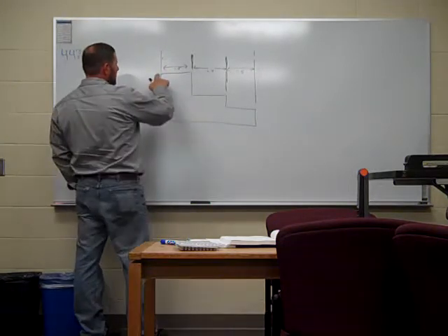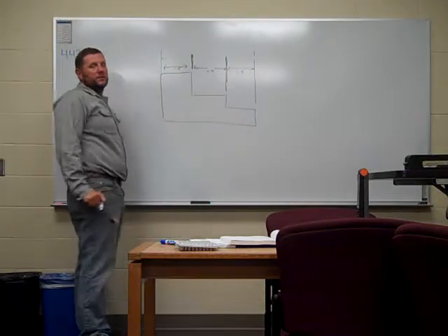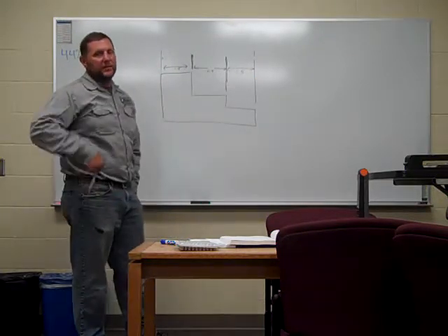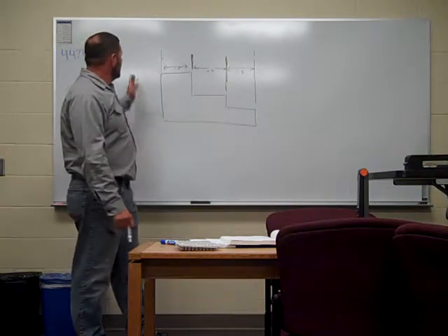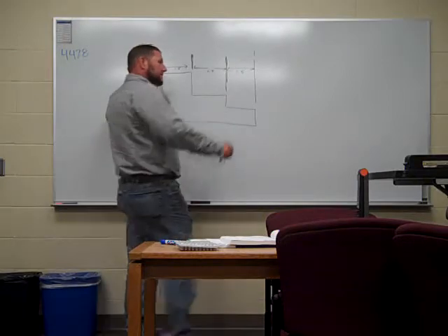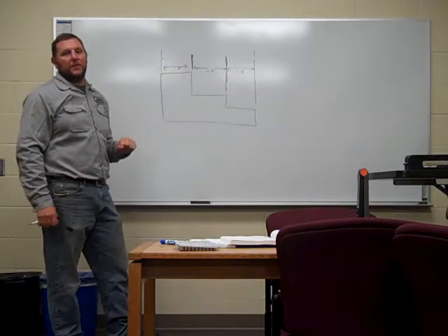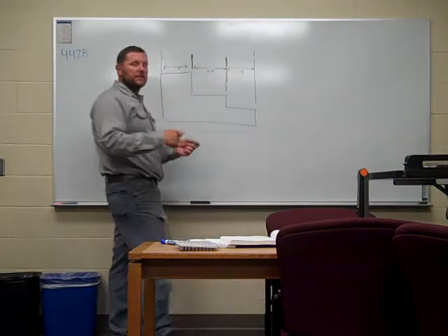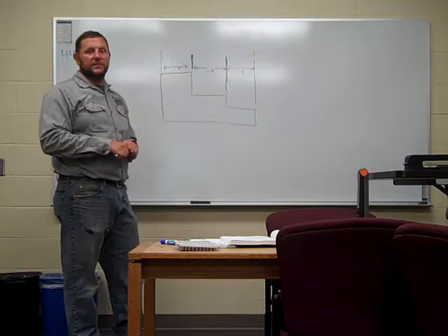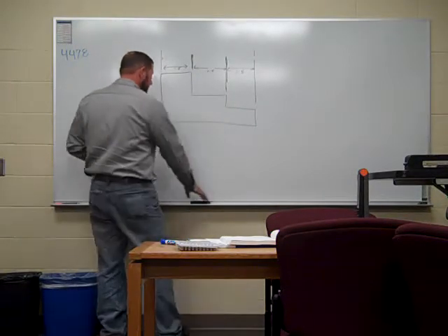If it was me, I'd lay the tape measure out here and measure all 3 dimensions from one point with that tape measure. Even when you get in industry and start fabricating parts together, make sure when you're measuring, you measure off one point, measure as much as you can off that one point. It's going to be a lot more accurate, instead of moving your tape measure 10 or 15 different times. Every time you move that tape measure, you have a chance of getting some error involved. Angular dimensions, I'm not going to go through all these.